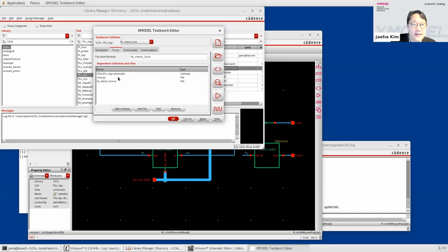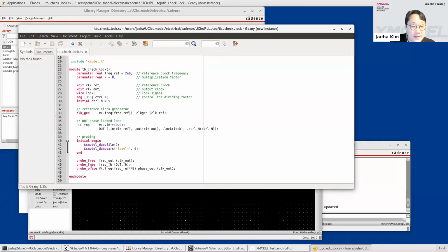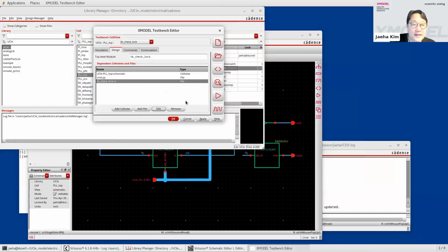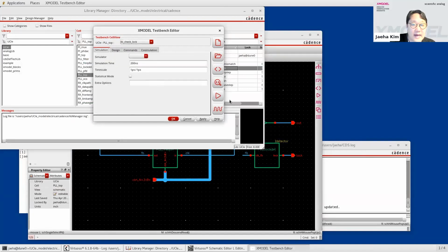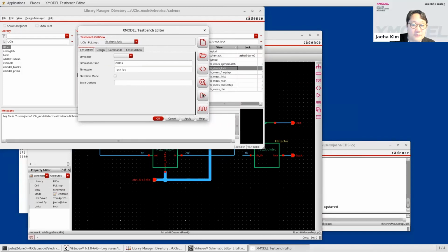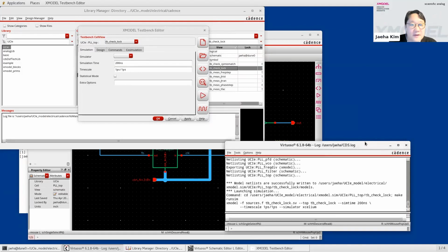Okay. And you can specify what is the dot that you want to simulate. How do you define the test bench around it? This particular example describes test bench in a source code format, feeding the stimulus and dumping the waveform, also measuring the frequency and phase of the clocks. And the nice thing about this is that once this is all set, to run the simulation, you just have to press this button right here. So all those settings and configuration are encapsulated in one single view.